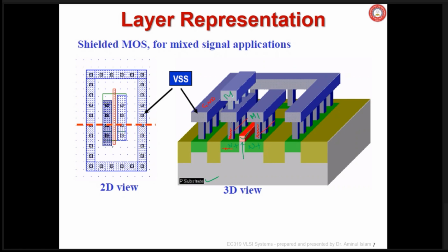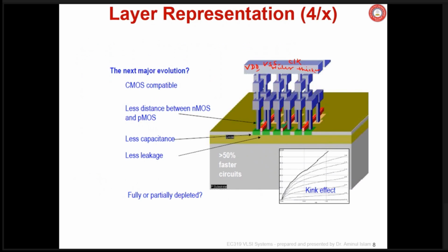Metal 2 line you see here, and this way it will go up: metal 3, 4, 5, 6, even up to 10. Sir, is every metal line separated by SiO2? Yes, mostly SiO2, but nowadays some other material, I mean other insulator, is also being used.